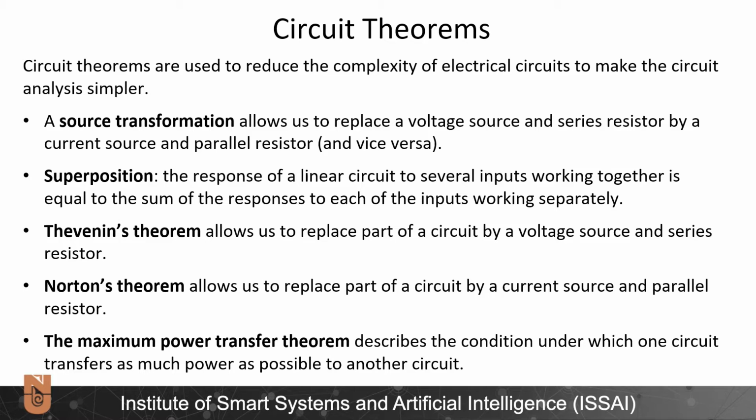In the superposition theorem, the response of a linear circuit to several inputs is equal to the sum of the responses to each of the inputs working separately. So we can simplify the circuit analysis by creating equivalent circuits and adding the responses of these sub-circuits to find the final response. In Thevenin theorem, we replace a circuit by a voltage source and a series resistor. Similarly, in the dual of the Thevenin theorem, Norton theorem, we replace a part of a circuit by a current source and a parallel resistor.